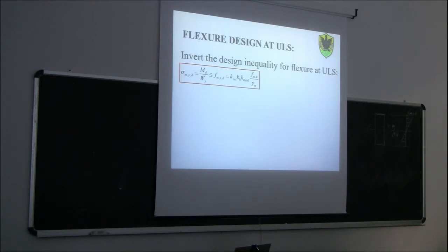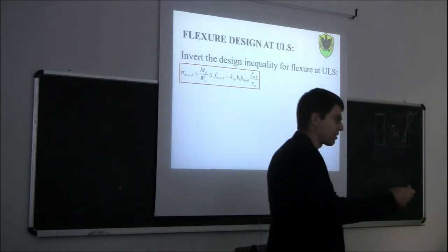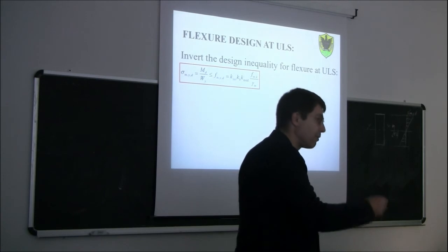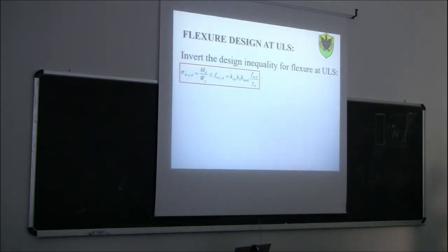So you are designing your beam for strength, but in order to calculate the minimum compressive strength, you could check the kind of environment where the structure was in. There was a table, if you remember, that gave you the minimum value of compressive strength of concrete in order to make the concrete durable in that environment. Okay, so you had that for reinforced concrete. Here instead we don't have everything. It's just based on engineering judgment.